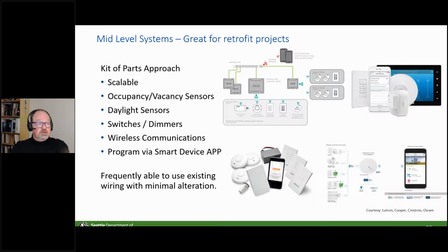So you don't have to really change the wiring at all. You just hot neutral ground to it, and then you do whatever wireless, wired 0 to 10 volt controls to your light fixtures, and wireless control between the switches and the sensors.